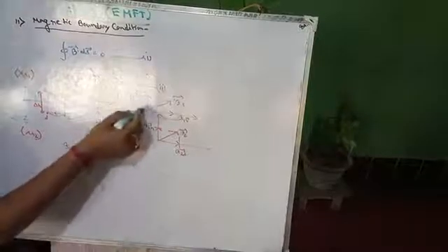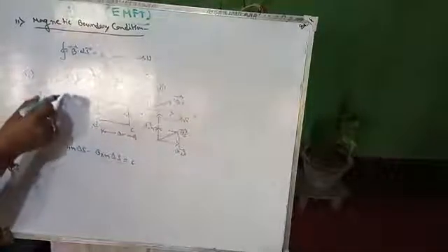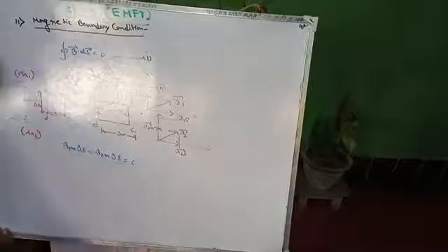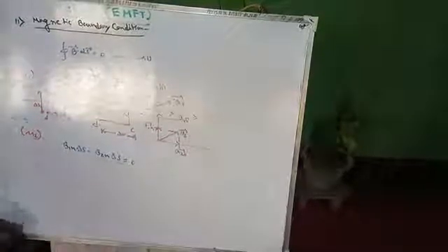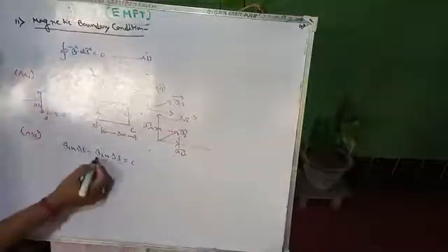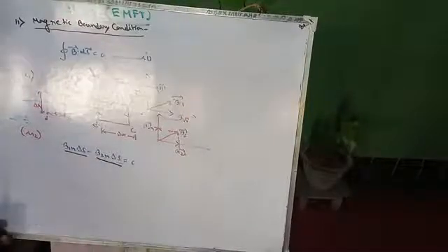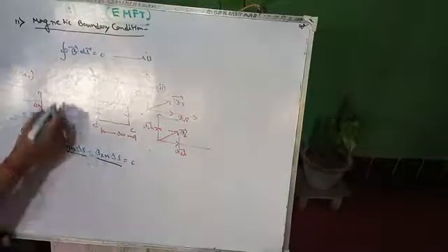Okay, so b1n is nothing but in this direction. So b1n multiplied with del s and b2n multiplied with del s, that means how much flux is emitting from that whole surface, which will be shown by the term b1n into del s minus b2n into del s. That means b1n del s is the amount of flux emitting from this surface due to the first system, and similarly b2n del s represents the amount of flux transmitted through the surface due to the second system. For this case we consider this del s and this del s identical.